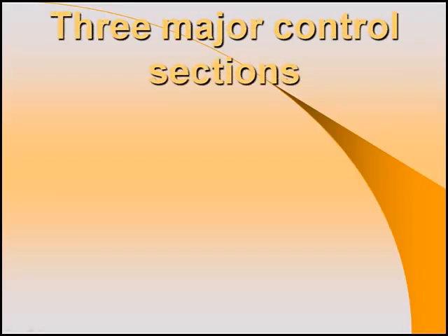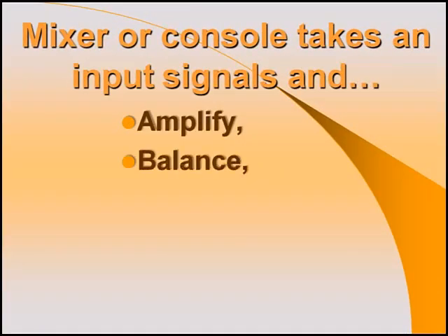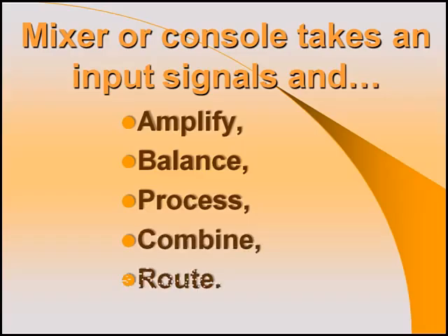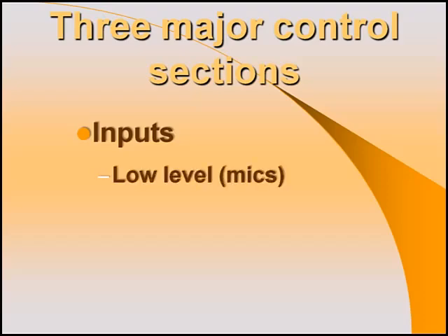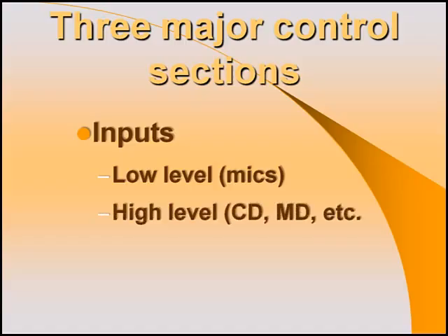Okay, reviewing console functions then. Consoles amplify, they balance, they process, they combine, and they route signals. Let's consider the 3 major console sections. Every console has inputs. These inputs are designed to handle 2 different levels of audio signals. The very low levels, such as those that come out of a microphone, and the much higher levels, such as those that come out of CD players, mini-disc players, computers, and so forth.